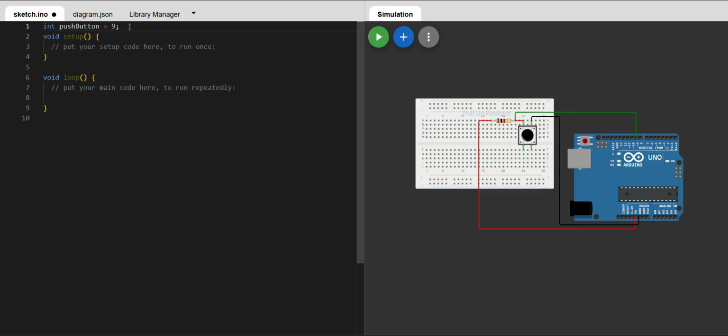When you are going to write to any pin, you shouldn't declare any extra variable. When you read from the outside world to the pin, you have to declare one extra variable to know the state of that particular pin, so I am declaring the button state variable.